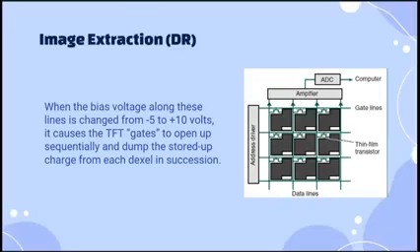Okay? So once the storage capacitor senses that it is at 10 volts, sorry, once the thin film transistor senses that the storage capacitor changes from -10 to +10 volts, it will open up. It will switch open so that the storage capacitor will then